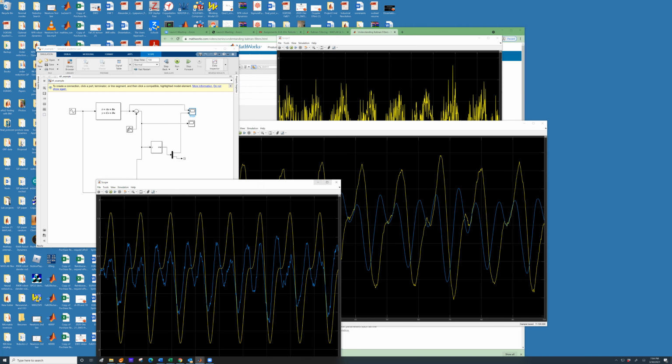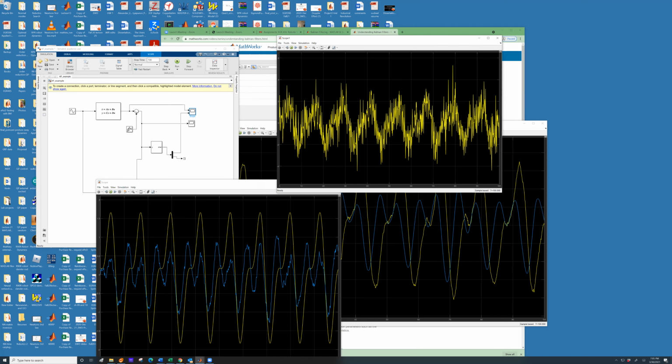So this is, do we need one of these? When you have a noisy measurement, and I think that is part we have to do in the next iteration. When you have gyroscope and accelerometers, they are not going to give you clean output. The output from gyros and accelerometer is always going to look like this, shown in scope 1. So somehow we need to filter it. So Kalman filter is one way of filtering it.